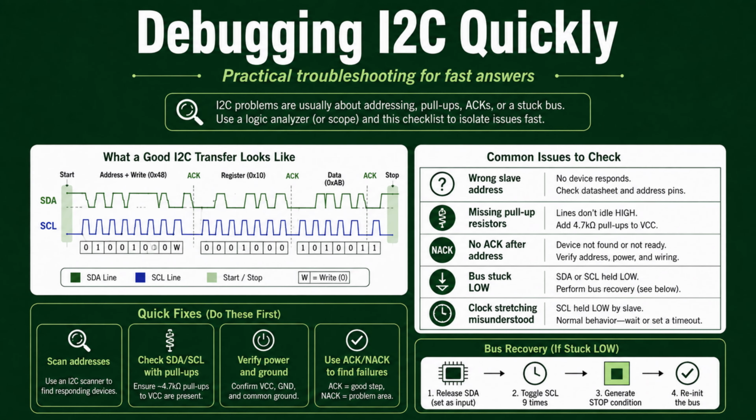When I2C communication fails, begin by checking the physical bus. First, confirm that the controller and peripheral share a common ground and use compatible voltage levels. Check that both SDA and SCL have pull-up resistors and remain high when the bus is idle.